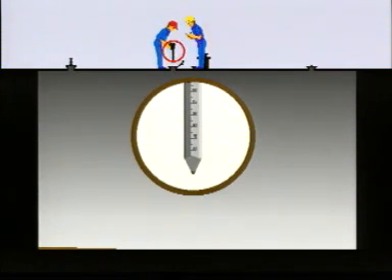If there is sludge or sediment found in the tank, take an average and use the innage table to find the volume. If there is a volume of oil in the aft part of the tank and a layer of 1 centimetre sludge or sediment is found in the most forward part, it's reasonable to argue that 1 centimetre of sediment covers the whole bottom and should be deducted from the volume of oil left.